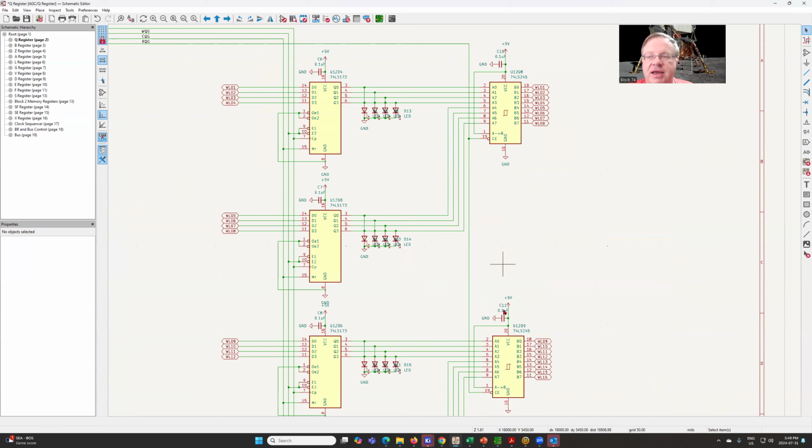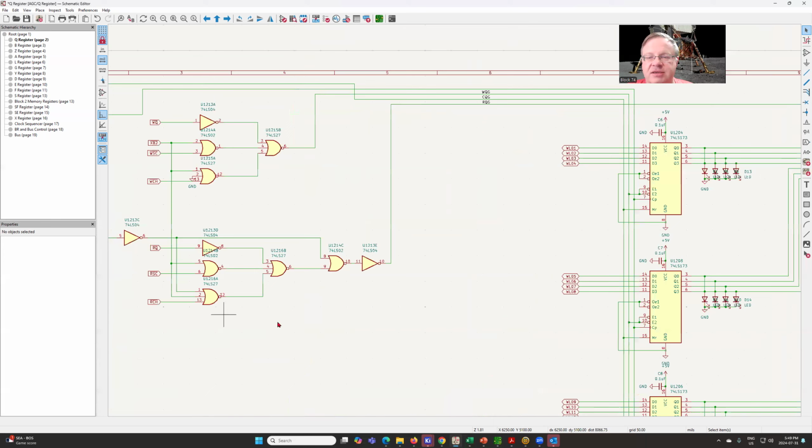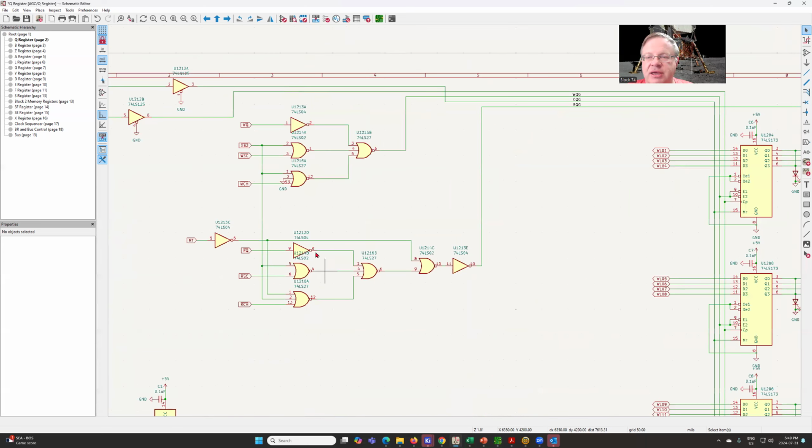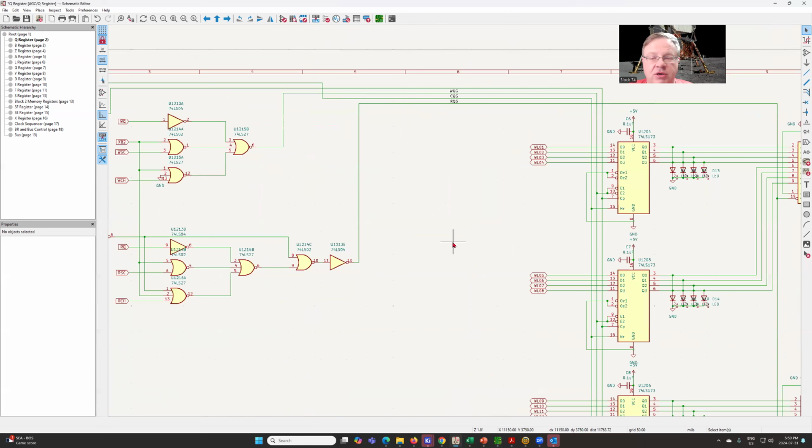Now, before, we actually had 2 sets of octal transceivers, one that we would use to write data out onto the write line bus, and then another set to write data out onto the channel bus. But again, channel bus doesn't exist. So this really simplifies things, and it just means the write channel, RCH, is just another mode that we can use in order to write data out of the queue register and onto the bus.